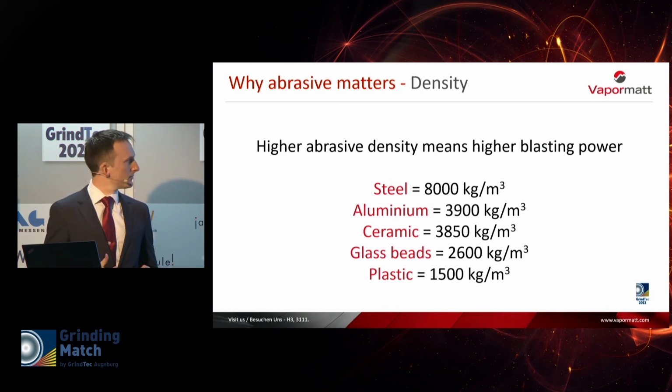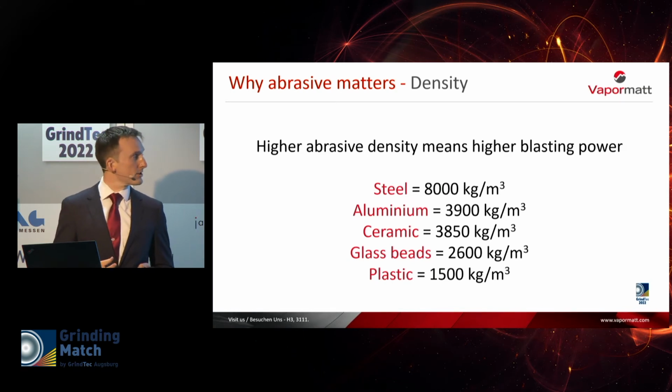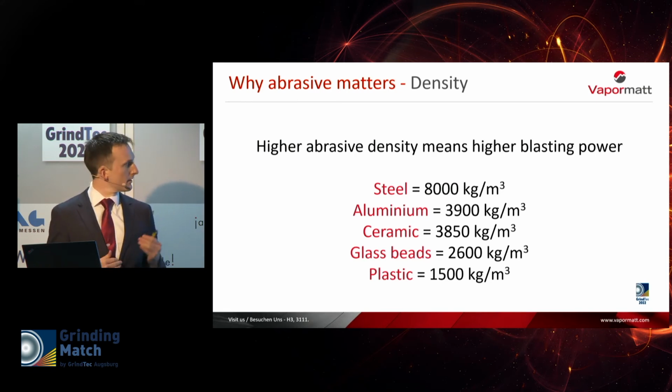It does benefit those who are looking to do lots of peening or putting stress into a part that helps increase the life, but it also brings its own challenges when used in wet blasting, particularly with the stirring and mixing of this slurry where we need to deliver a very dense solution to the blast guns. To manage this, we have to have a good understanding of how the particles behave and how they settle within a liquid, as the difference can be as much as 50 to 70% in settling speeds.